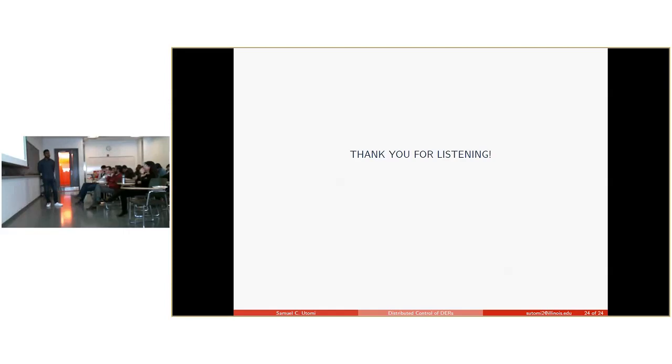What's the sampling frequency for those simulation models? The simulation step is 2 times 10 to the minus 4, so 200 microseconds. And then your switching frequency for your control loop is also 200 microseconds? No, I can't give you much detail on the controller frequency. So 200 microseconds is your time step for your simulation state step in Typhoon. Yes. And what's your control loop frequency? Your microcontroller is controlling, how often does it send a control signal?